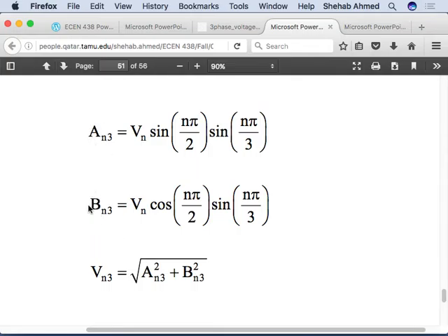Right? It's all about power quality. Inverters is all about how you differentiate between sinusoidal PWM and programmed PWM. Where you've programmed a few pulse widths, you differentiate between them with the harmonic content. How do you look at harmonic content? Fourier series, like we did just here.